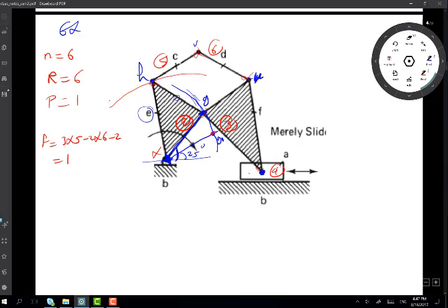So I know G prime 100%. Then with a circle whose radius is the distance GH, I can find point H on the red locus. So over here, with this center, I can draw another locus for H. The center of this green circle is G prime, and the radius is the distance GH, and this green circle intersects the red circle at some point.